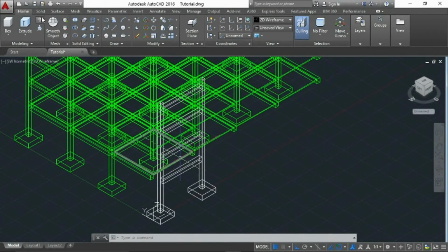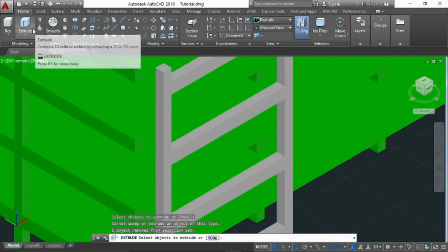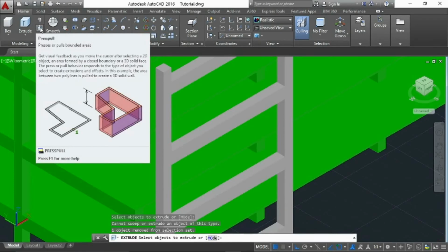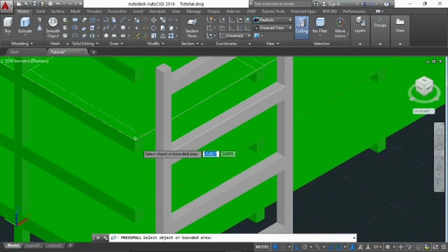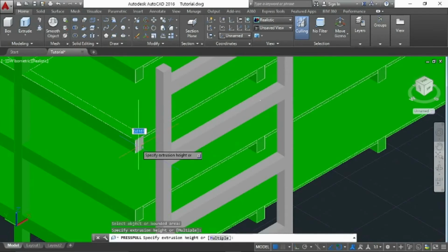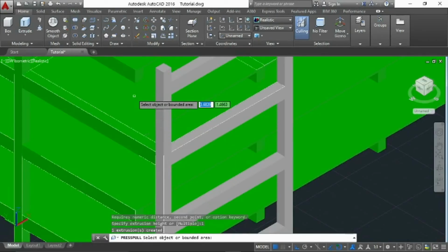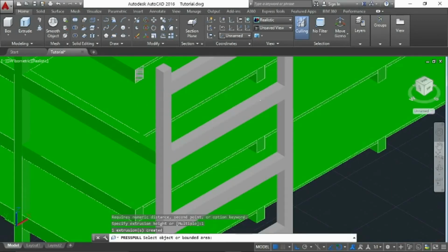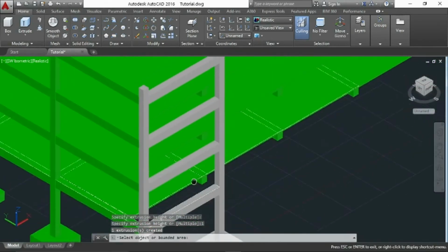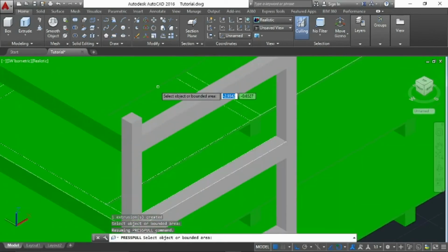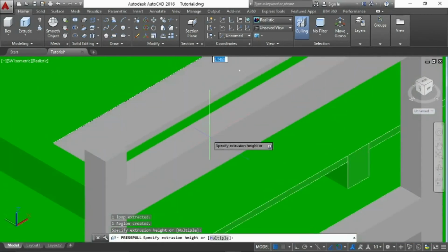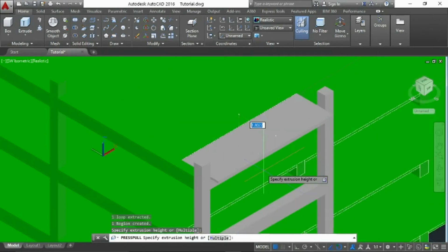Then go to View, click the press pull icon, click a surface, that surface, enter, then type 1 because we offset that by 1 meter. So that is already connected. So click also the other. Just click one. Enter. Next, your slab. Remember your slab. There. Pull toward the beams. Enter one. Enter.